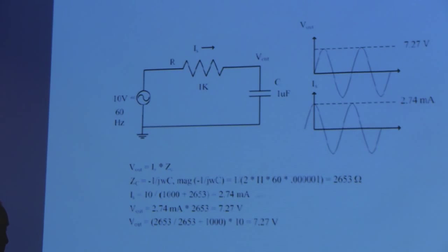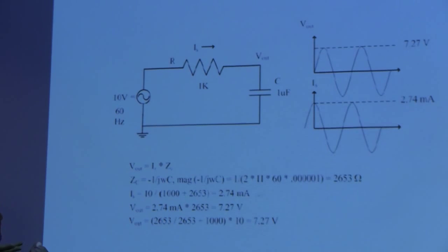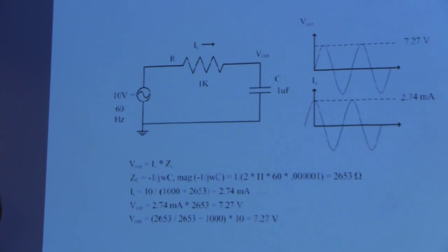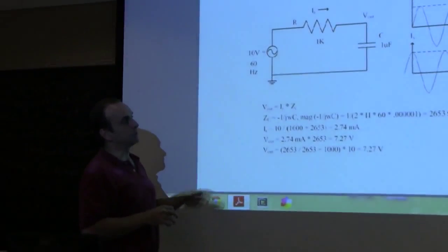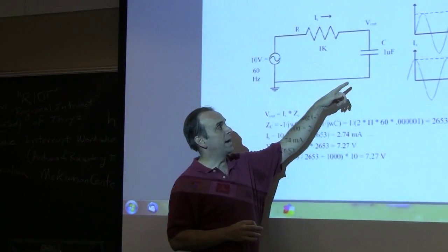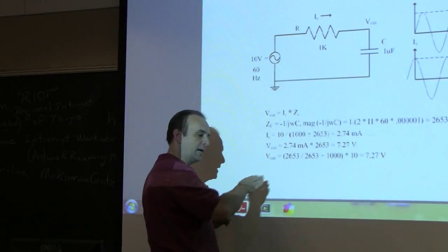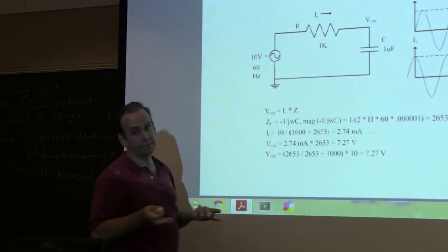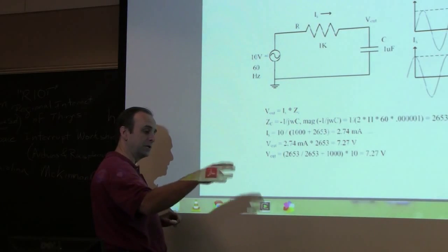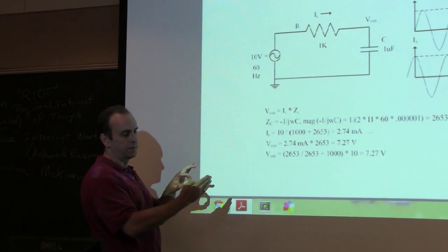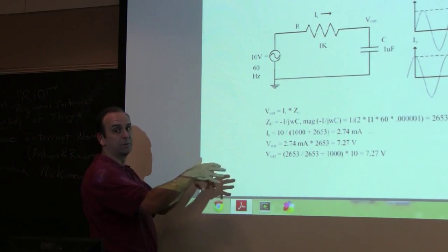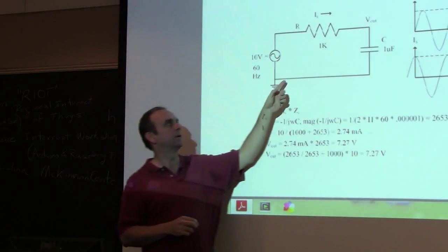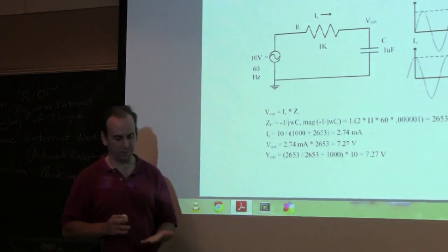And then I want to look at, so what's this other junk? How high is it? Is it very, very small and therefore I don't care? Is it significant relative to the size of the signal I care about? Well, then I care and I need to take action to diminish that frequency. And so I can get fancy. I mean, this is a low-pass filter. This says basically everything that's low is good, everything that's high is bad. You can make high-pass filters. So you're basically saying everything that's high is good, what's low is bad. You can make notches. So you say, I like the low, I like the high, I just don't like this area because I need to get rid of this energy because I'm doing something here. So you can tailor this. This is the simplest filter probably.